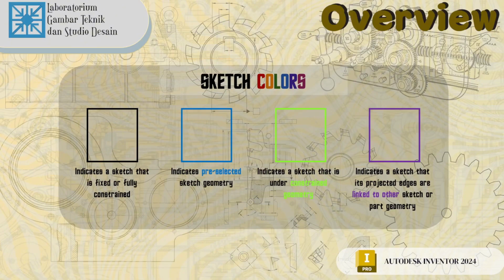Next, we have sketch color. Black sketch color indicates a sketch that is fixed or fully constrained. Blue indicates pre-selected sketch geometry. Green indicates a sketch that is under constrained geometry. And the last one is purple. It indicates a sketch that is projected edges are linked to other sketch or part geometry.